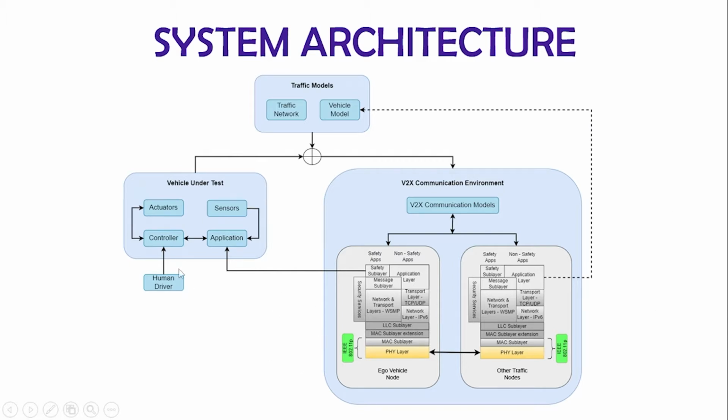The vehicle under test can be controlled by a human driver according to the sensor inputs or customized commands like V2S messages. Since it is complex to implement a vehicular environment using a number of such real vehicles, we use a traffic modeling simulator to add the traffic into the simulation environment. The VUT is inserted into a simulated vehicular environment that is generated by the traffic modeling simulator.